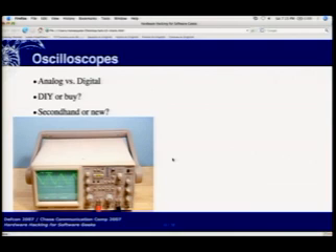You can build your own oscilloscope, but chances are the bandwidth is not going to be fantastic. It'll probably be good for audio work, possibly for some TV work, but you'll start to lose it around RF, and it certainly won't do 100 megahertz buses on modern microprocessors. Buying them can be expensive if you're getting them new. Secondhand ones are good if you can make sure that it's working. It probably won't be calibrated anymore, and if it's too old, you don't want to get anything less than 100 megahertz, because 100 megahertz is pretty much the low end for being really useful for a lot of stuff.